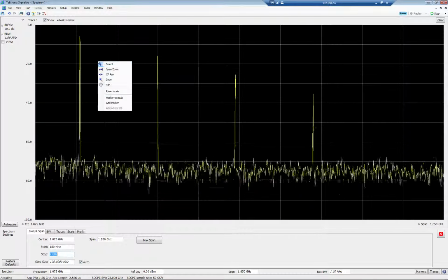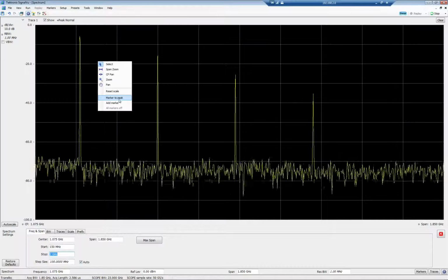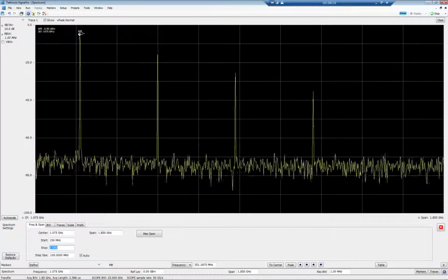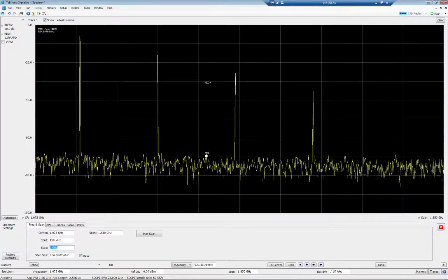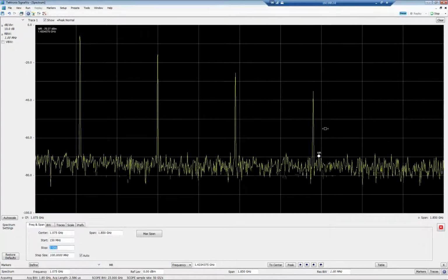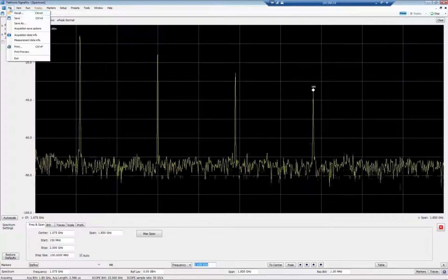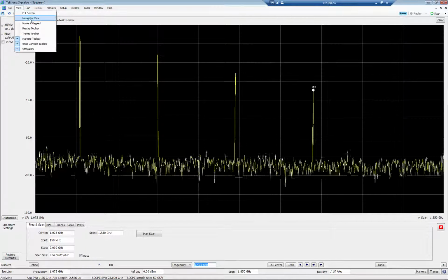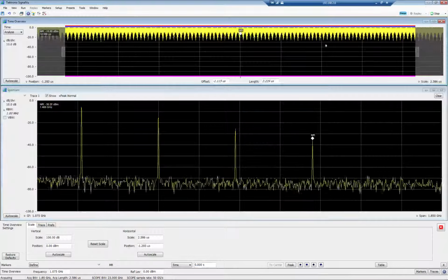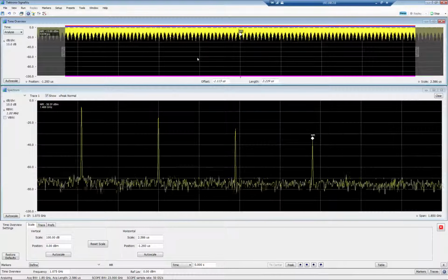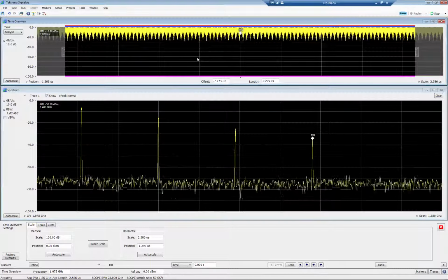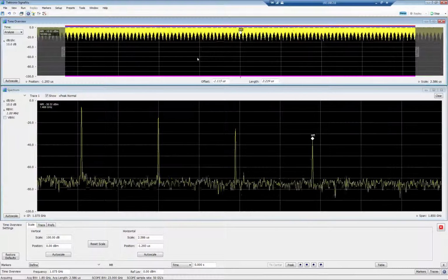And here are waveforms, so I can add a marker to peak, and you can see that's 351, and mark 20, 705, 156. So these are pulses. If I view this as a zero span, you can see it's almost always on. But our pulse that we were meant to do should have an off time, which was really long.